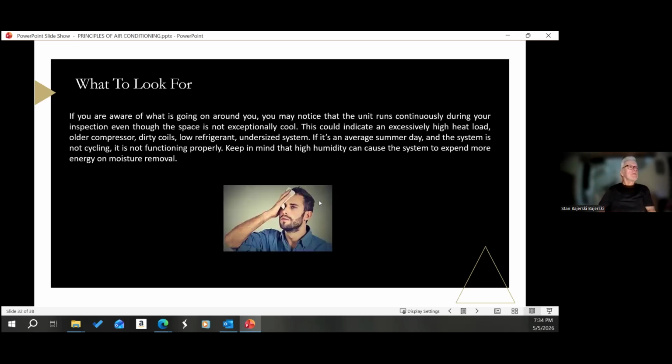So when you're in a house and you're aware of what's going on around you, if I have to start the unit, I'm going to try and pay attention. If it's really hot, I'll start it when I get there, so by the time I get inside, I'll be a little cooler. If it's running already, I'm going to pay attention when I get inside, and try to notice: is it continuously running, or is it cycling?